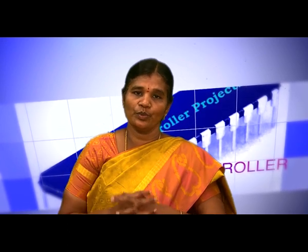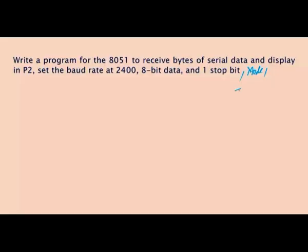Right. So for this program, what are the things we have to do? First we have to activate the timer mode, then find the equivalent baud rate, then SCON. These 3 things you have to calculate, and only then can we start to write the program.